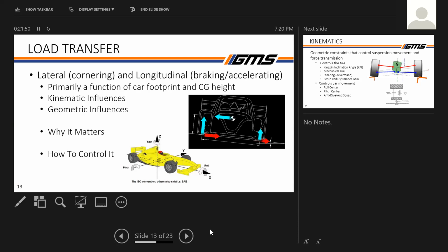Secondly, it affects our yaw acceleration and how easily we're able to turn. The tire is the farthest thing from the center of gravity of the car. So some basic physics, like R cross F, the radius is far away from the center of gravity, so that means the force is highest there. If we make that lighter, then there's less force there, so that makes the car rotate easier. Also makes us able to turn easier.